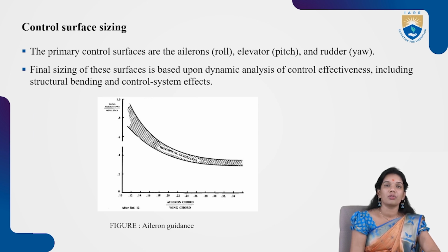Then with respect to the fuselage length and gross takeoff weight, I have parameters that are constants for different types of aircraft. I take those from there and calculate the fuselage geometrical sizing. Then with respect to the wing, also the same. Again, with respect to the tail volume coefficient, we take the main wing chord or wingspan. Then we calculate the horizontal tail and vertical tail coefficients with respect to the yawing moments and pitching moments.